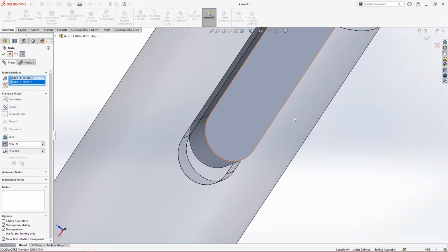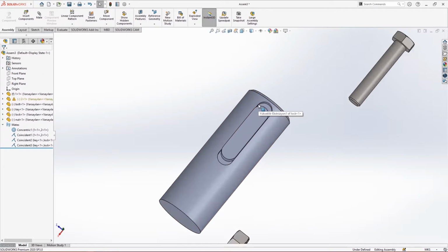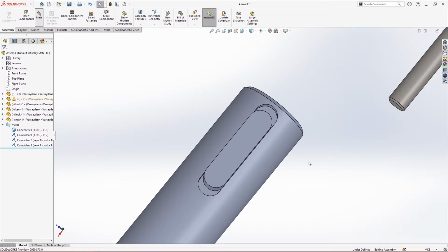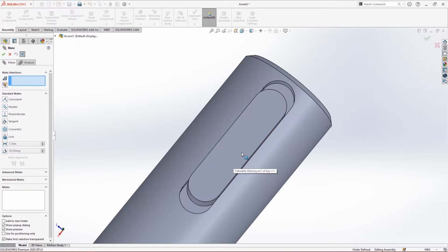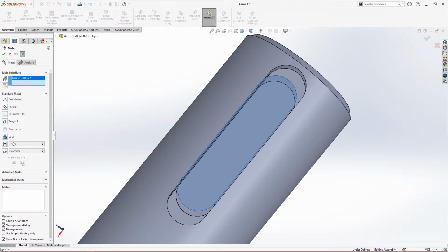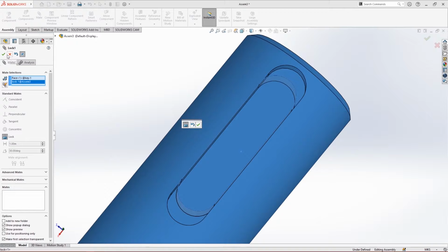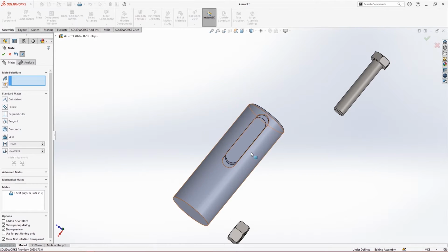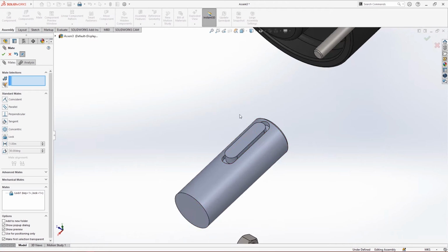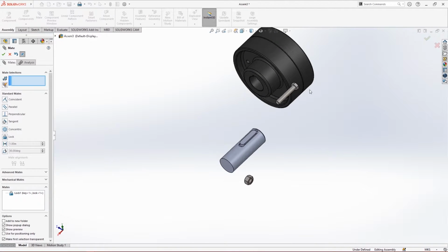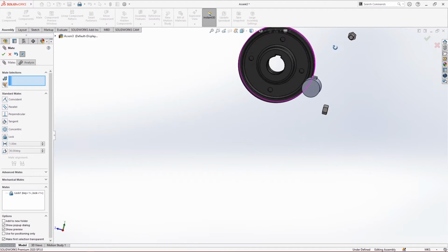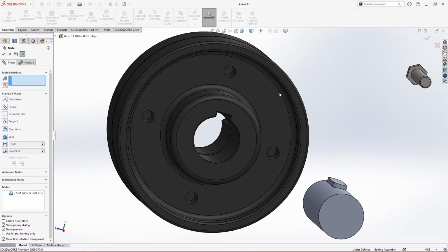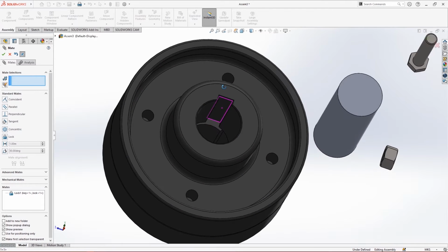Now, so once we fix that, another way is, if our calculation says that this key is in the center, you can just click it and lock it. So you can select both and just lock it, so it will not move. So both of them will act as a single entity. So we are done with the lock. So we can apply our lock. So the lock will be applied here in the center.